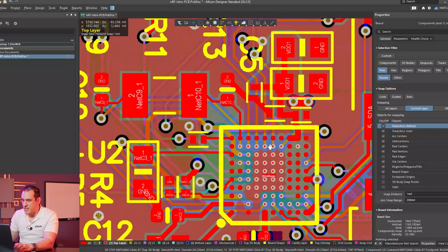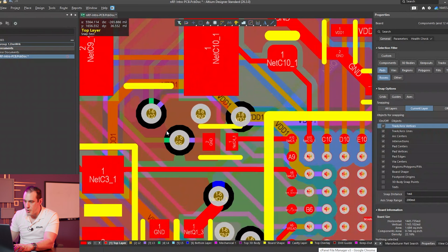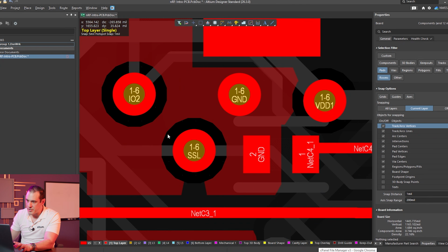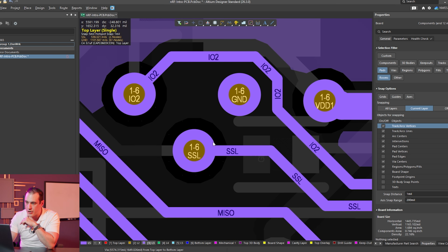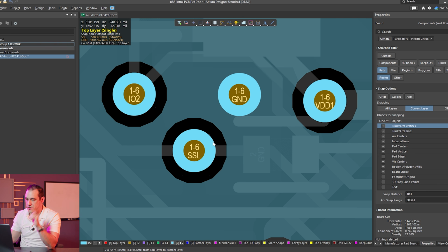Now inside of Altium Designer, this would refer to this small section of copper right here that we see for these two vias. Now these two vias aren't part of a differential pair, but the same constraint still applies. If I want to maintain continuous ground between these two vias, I'm only allowed to do that if there is some minimum amount of copper in between the two vias as defined by this antipad. And we can see that here even on the internal layers. So right here on layer 5, you can see that we're maintaining some copper sliver in between these two